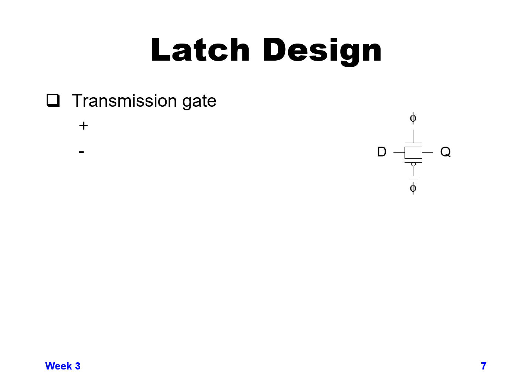A slightly more complex latch design is to use a transmission gate. So instead of using just a single transistor, you use both an NMOS and a PMOS transistor. An additional bonus to this compared to the previous one is you don't get any VT drop. You still have all the cons of the previous design that were mentioned, and one additional con to this design